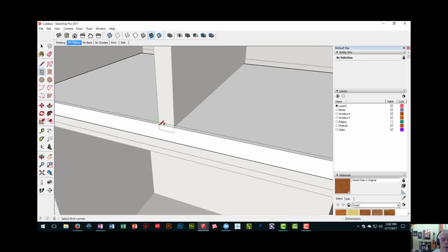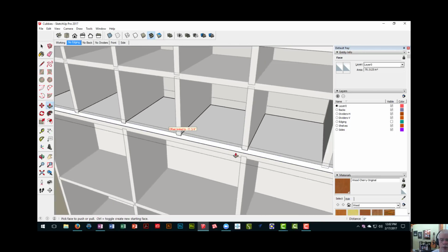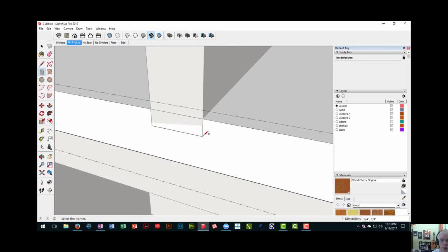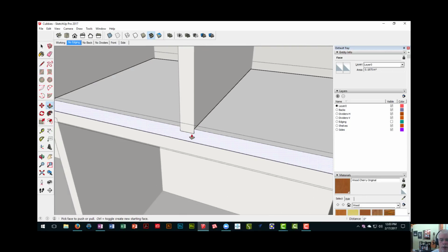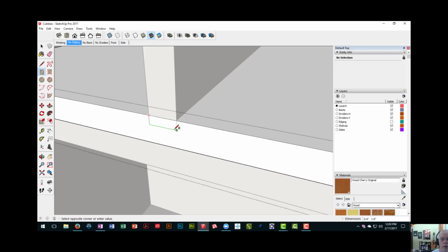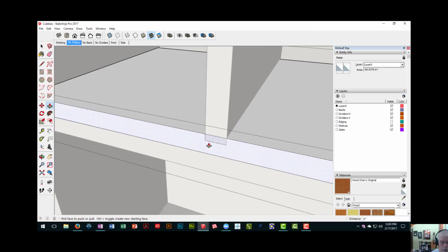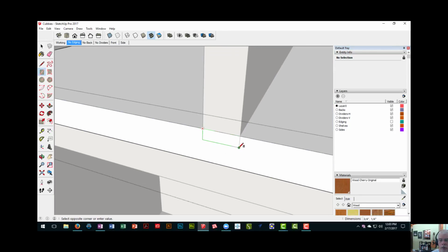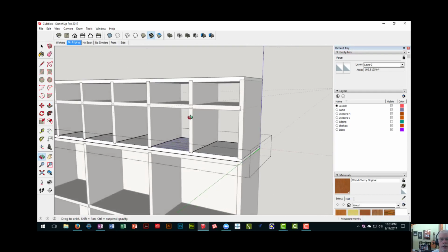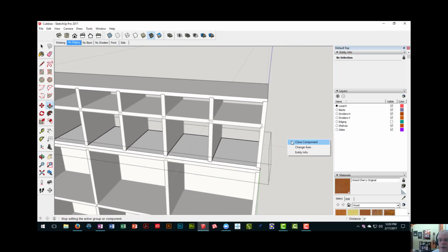Okay, so you've seen this a bunch of times, so I'm going to go rather quickly through this, but just showing you that if you use hotkeys, R for rect, P for push-pull, and double click with the push-pull, you can do this pretty darn quickly. And remember, I'm doing this automatically on the top piece. So great. We've got all those dados cut.